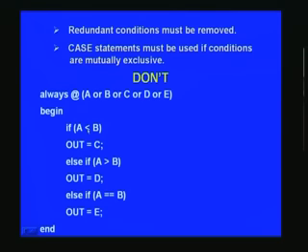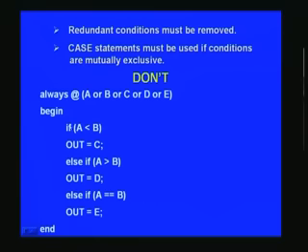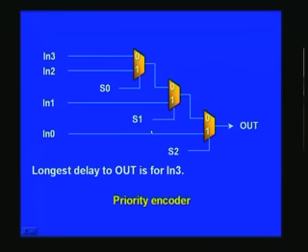So, I will tell you. See, A less than B: if this is not satisfied, it goes over here, then it implies that it is either equal to or greater. So, this statement takes care of the next possibility, and what is left is only equal to here. So what is known? Why do you want to put another condition here which is already known? If you put this condition, what happens? It creates one more additional mux, as we have already seen. One mux for this if statement, then else if one more mux, and one more mux here, as we had seen earlier, precisely the same thing.